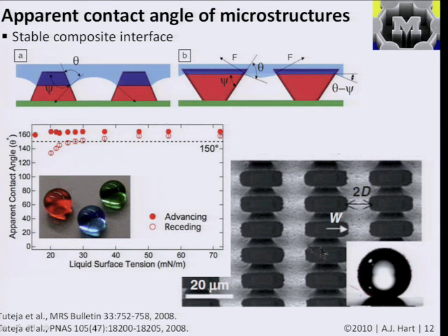And this is just an SEM image of some of the example surfaces that they made by microfabrication, by etching a silicon wafer such that they undercut a thin film. And these hats sort of allow the fluid to come a bit underneath, but keep an overall non-wetting profile and a high apparent contact angle. And as a result of that, the liquid rolls off very easily.